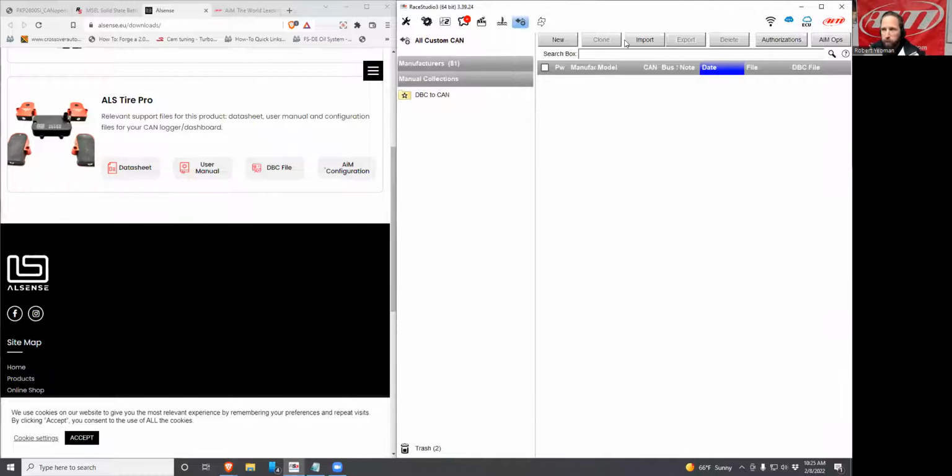and our next step in the process. So we have to take this DBC file that we have and import it into the software. And before, we would have to do it longhand. We would have to open it up in a DBC editor and Notepad and manually transcribe the information that we had from here into our software.